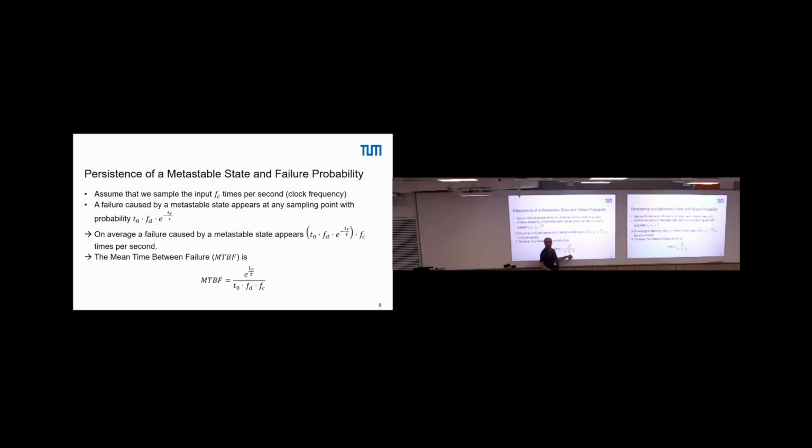But if we reduce the data rate, that means we take longer for the overall transmission, so we will not win anything. We can also try to impact the clock speed of the receiver clock. That can have a little bit of an impact, but at the end, we run a system on the maximum clock usually, so we don't want to reduce this.